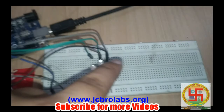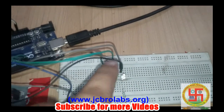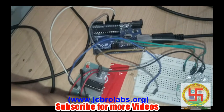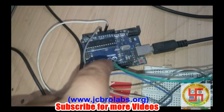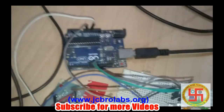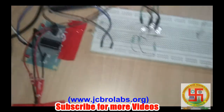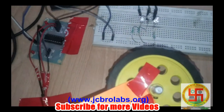Now we have also connected two LEDs, a red LED and a blue LED, and the same are going to the input pins of this L298 IC. These pins are connected to pin number 8 and pin number 9 of the Arduino. So we'll be sending 1 and 0 to pin number 8 and 9, and corresponding to this, the DC motor will be rotating in either clockwise or anti-clockwise direction.